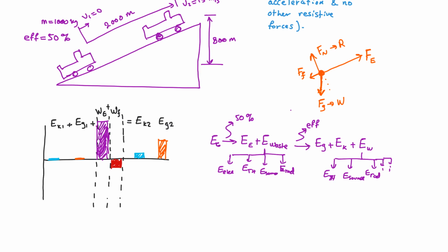And because of this waste energy, we're also going to have some sort of efficiency here. We don't know exactly what that efficiency is at the moment. If the frictional forces are really, really high, this efficiency is going to reduce. If the frictional force is very small, you might have an efficiency of 95 to 100, or anywhere between 90 to 100. But if this frictional force is very, very large, the efficiency could drop to lower numbers like the 70s or even less. And the useful work we're getting out of this is a combination of these two.